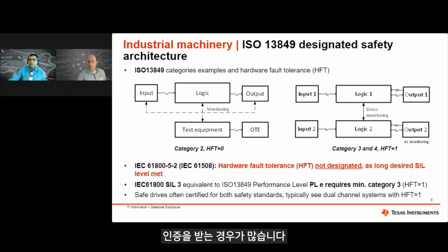In that case, we go to the IEC 61800-5-2 for variable speed drives. If we refer to table D5, we see signal isolation components. So the IEC is generic on isolation and does not specify the type of isolation, whether it's optical, magnetic, or capacitive anymore.